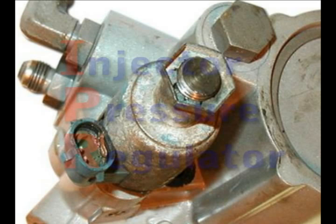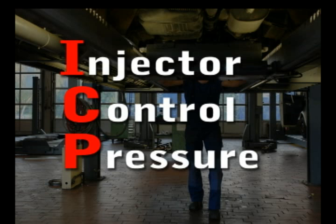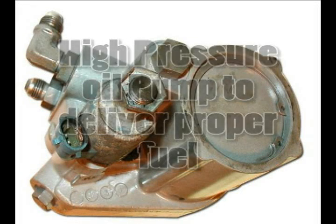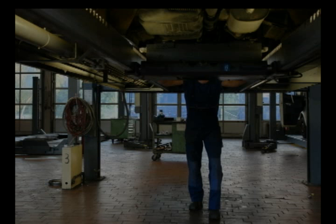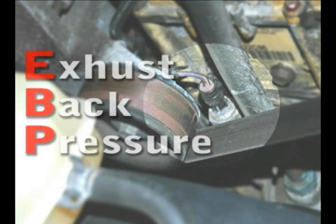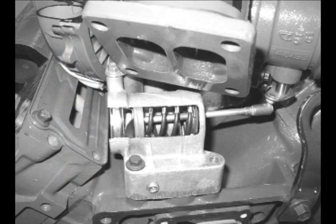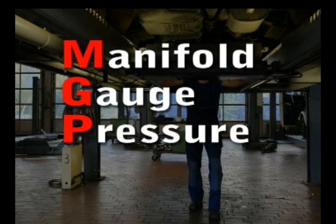IPR, or injection pressure regulator, and the ICP, or injection control pressure, will verify the power request and the ability for the high pressure oil pump to deliver proper fuel. The EBP, or exhaust back pressure, and the EBPR, or the exhaust back pressure regulator, will verify a restriction in the exhaust system or a malfunctioning regulator. And then last, the MAP, or MGP, will verify boost and therefore give us an indication of engine breathing.